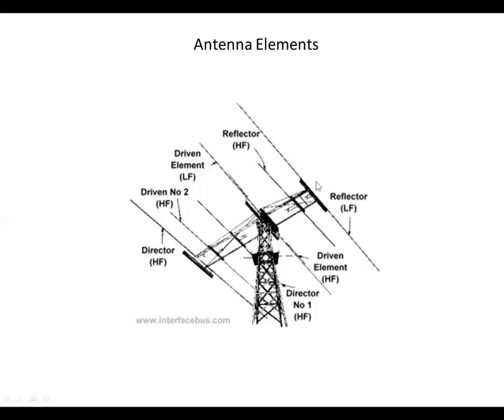Now they talk about gain in an antenna, and it's important to understand the gain in an antenna isn't like the gain on an amplifier where you turn the knob up and you get more power out. With the antenna, the power you're pumping into the antenna is pretty much constant. What you change, rather than the power level, is the focus of the power.